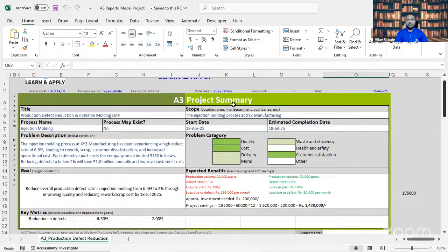The injection pressure is not consistent across production runs. The production pressure regulators often go out of calibration, right? So we identified the root cause is that the current calibration SOP does not cover calibration of pressure regulators. For the second one, I also added the lack of training and SOP on measuring and responding to tool wear. These are the two RCAs we've seen, and I just added the information here. Is it clear up to this point?